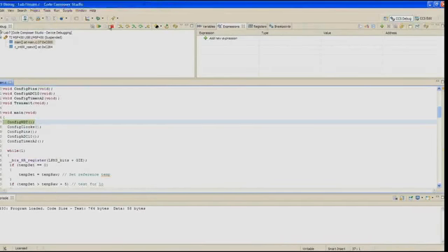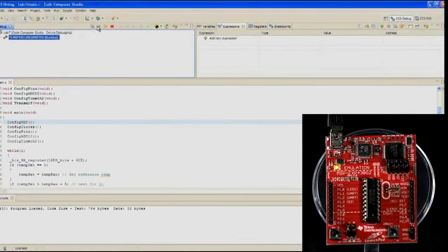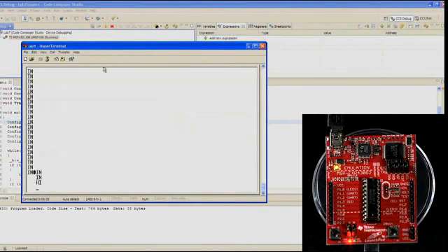Make sure your code's running. Minimize Code Composer, and run HyperTerminal if you're running Windows XP. If you're running Windows 7, you need to use Tera Term or your other favorite terminal program since they removed HyperTerminal. In HyperTerminal, give the new connection a name and click OK. In the next dialog, select the COM port you found in the previous lab step in the Connect Using box. Click OK. So in your terminal display, you'll likely see IN, as we see here, displayed over and over again.